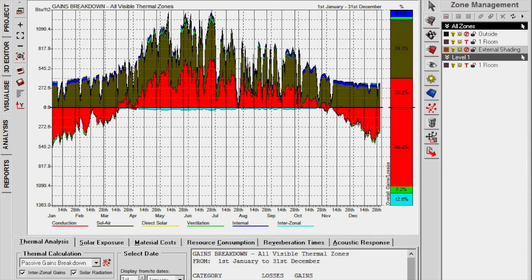Okay. Conduction, that's the amount of heat that's flowing through a surface. So we'll often talk about a wall having a certain R value or a certain U value. And that's okay. We can really talk about it either way. Just different parts of the world like to talk about it differently. Basically, you need to know that R is equal to 1 over U. Okay, so when we talk about an R13 wall or an R19 wall, anyone have their calculator handy? Like, what's 1 over 13? Any calculators? Lottie, Raj, anyone?